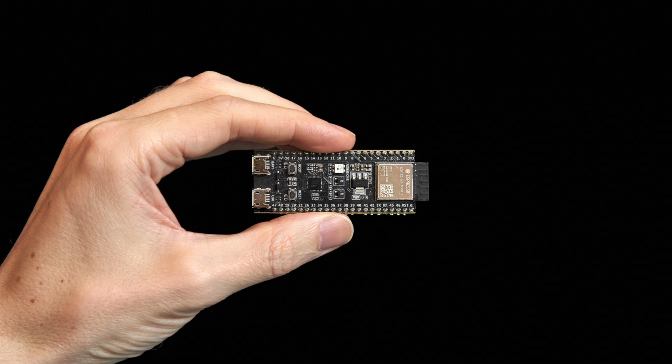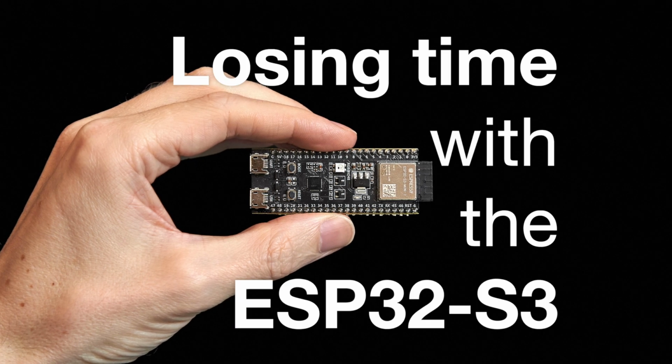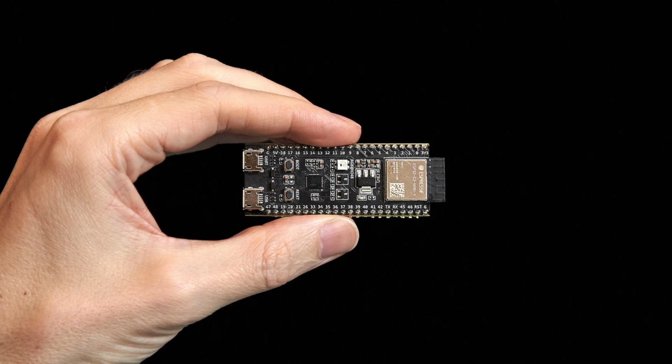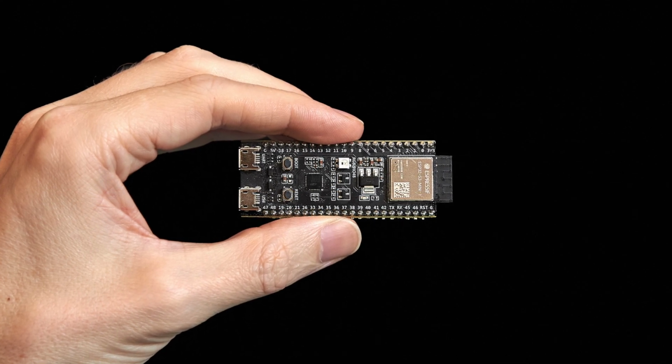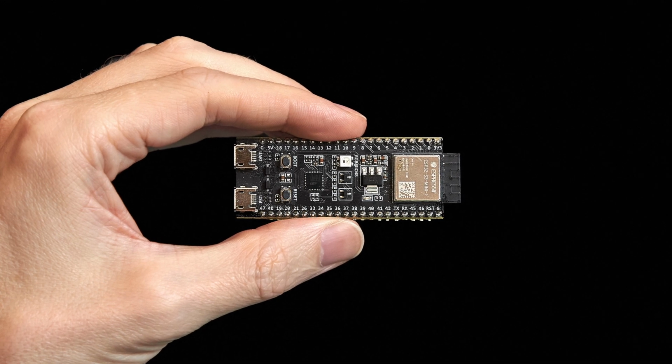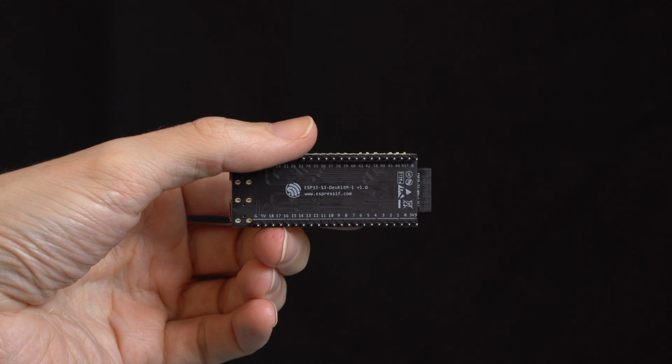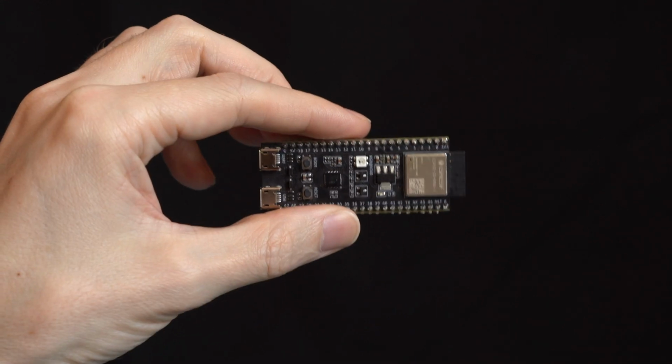Hello. Today, I would like to talk about the ESP32 chips and some of their pitfalls with timekeeping. Their clocks are often good enough, but for some projects you have to be aware that they can drift by minutes in just a couple of hours. I'm going to focus on the ESP32-S3, but everything is valid for most ESP32 chips.